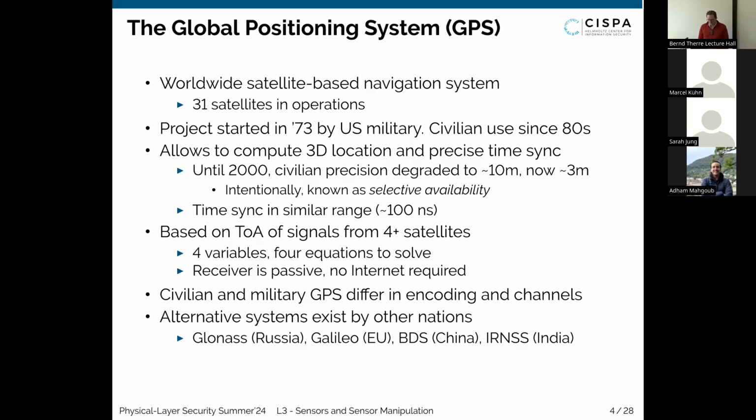It is maybe obvious, maybe it's not obvious, but the GPS satellites themselves do of course communicate with ground stations, but they're just broadcasting signals that are then received by the GPS receivers that you might have. So your GPS receiver in your phone or in your car is not directly communicating back to the satellites. Your GPS receiver is also not talking to any other GPS infrastructure. It's just one-way communication, broadcasting signals that are sent out from the satellites to your receivers.